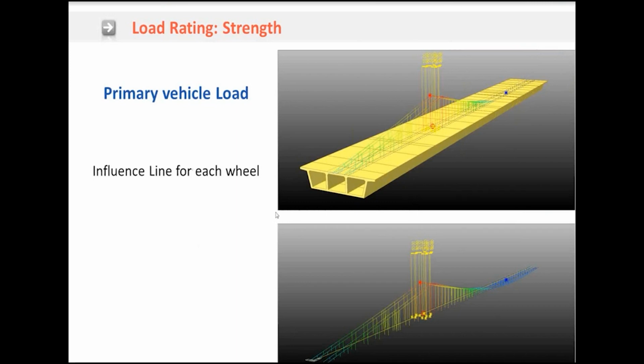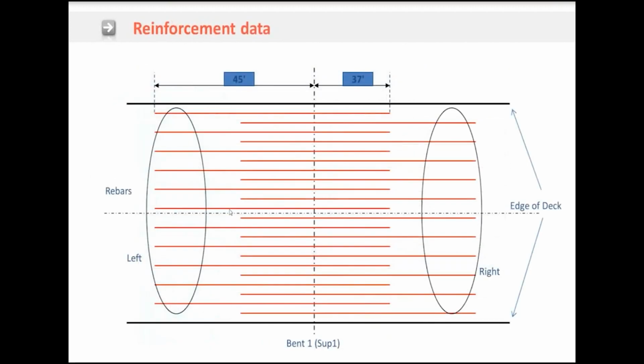Here's the thing also for the moving load analysis. It doesn't matter how many wheels or how many axles you are defining, MIDAS actually performs the influence lines for all of those axles and all the wheels. So you get a pretty accurate result. It doesn't go with the assumption or summary of those things.